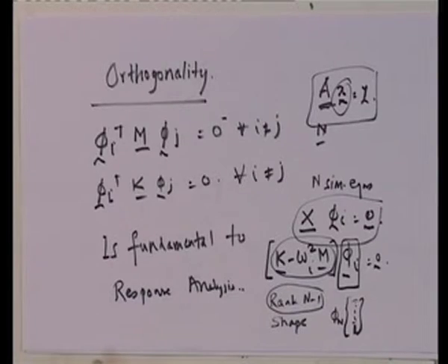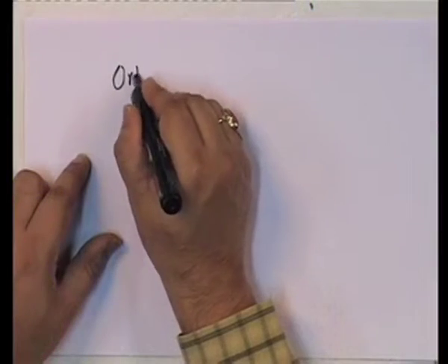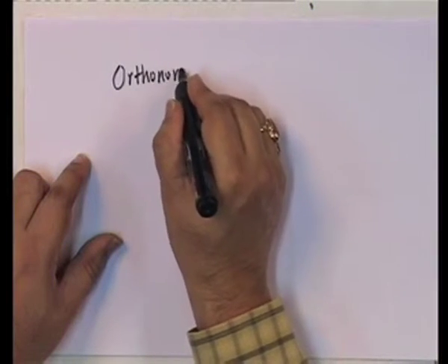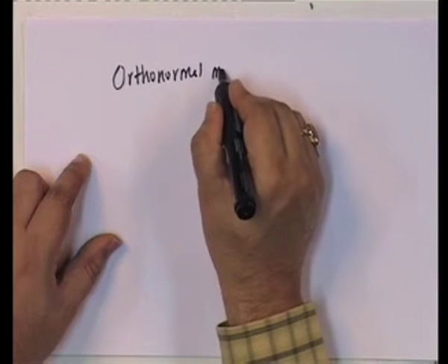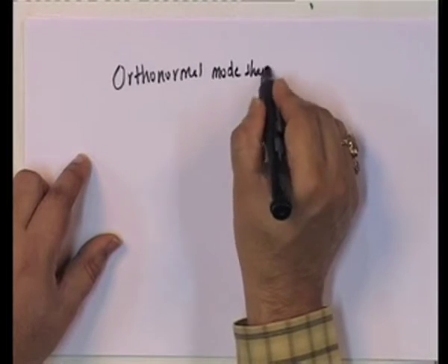Okay. So, now a lot of people say, well, what do we do? Well, you look at the mode shape and you choose the highest value as 1, so that every other value is less than 1. Now, my question is, these are all fairly random processes. So, therefore, there is a specific type of mode shape which everybody would get the same, and that mode shape is called an orthonormal mode shape.